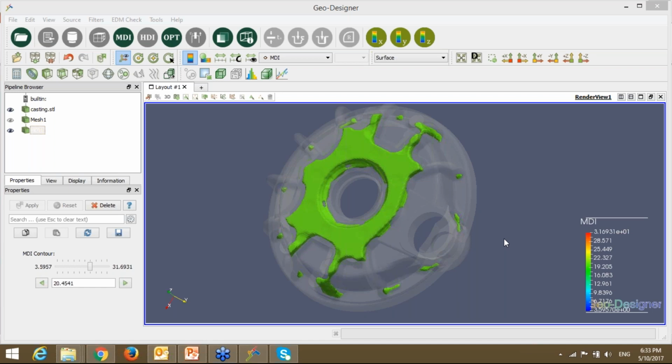The basic principle in the casting part is, if you do not have an external cooling effect, that means you don't have external cooling in terms of chills, or external cooling in terms of a cooling channel like you have in high pressure die casting or low pressure die casting, then whichever region has the higher mass will solidify last, and that is the region which is likely to get hotspot and shrinkage. This is the basic concept when we speak about the sand casting and investment casting process.